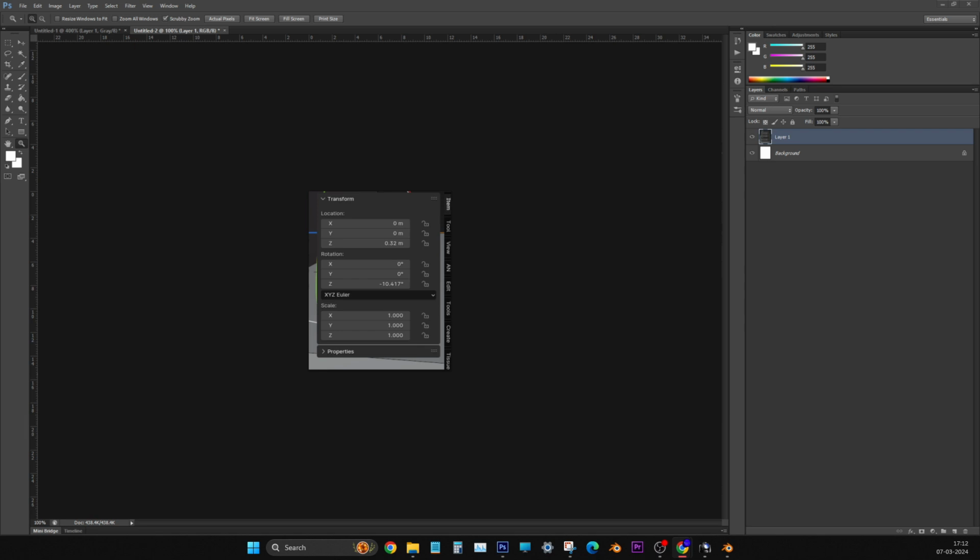So go to the original step, down. The original step is the first down step. This technique I'm telling you will always be useful. Wait, go to edit mode. Press any vertex where you want to zoom in. There, that side. Okay, this side you select, inside. Now press dot. Yeah, see, the camera is already there. So this way you can zoom in. It's a kind of technique only. That's all. Right, now turn the camera.